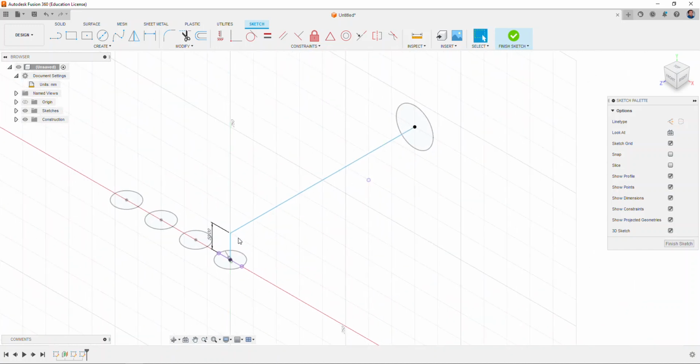The issue that we're going to face if we don't do this first is we need a little bit of a bend right here, or a fillet, and we're going to put about a 40 millimeter fillet there just to give it a little bit of relief. Otherwise that loft command is going to collapse in on itself and it's going to give us some errors. And in here it'll tell you some of the constraints are removed.